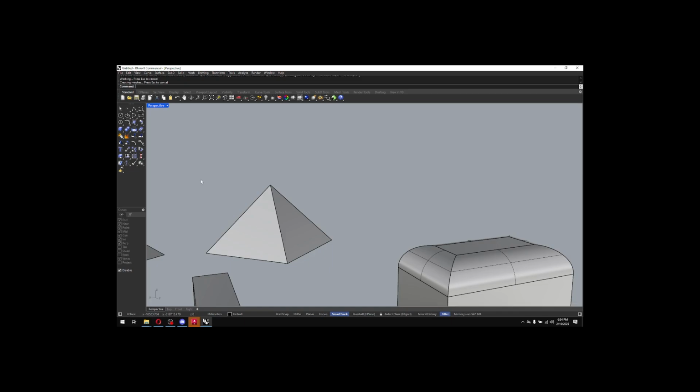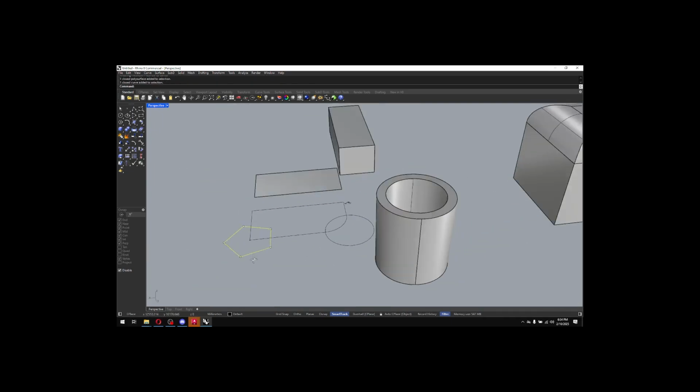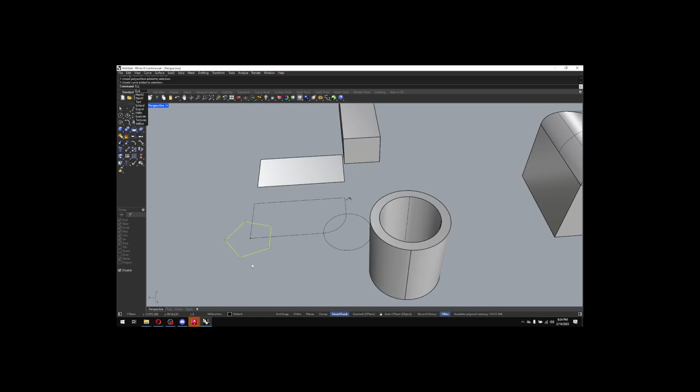Let's see. Let's cover what are some of our other basics that we need. Explode, just like AutoCAD. But now we've also got shapes, not just lines. So if I explode this guy, I would assume you all would think that we just are going to get 5 segments, and that's correct. Then from there, just like in CAD, I can select 2, J for join, it's going to join those. So now this is a double piece. At any point, I can click again on one of those points. It'll highlight that point separately, and I can move that around if you need to.